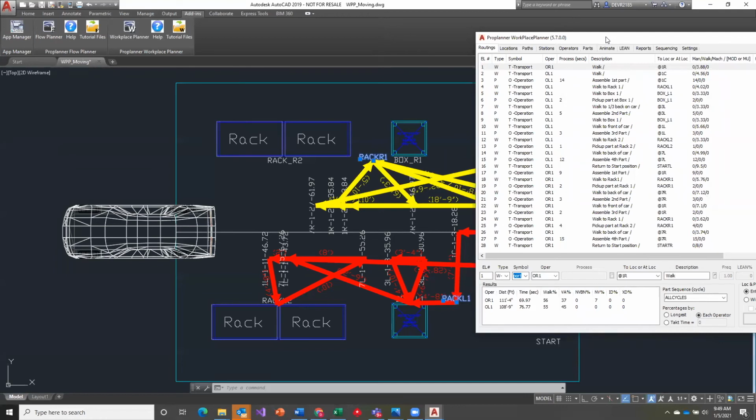Now, the problem with the assembly line balancing study is it may have estimates for walking, but it won't know the actual walking because in line balancing, you're moving the task to the station. So this is really a post-line balancing validation of cycle time, taking into account walking. So yes, in the line balancing module in Assembly Planner, I can export to Workplace Planner the list of tasks and task times and task descriptions for each operator in this station. And then I do my calculation, the software updates the walk times, generates the diagram, and gives me a much better view of my cycle time.